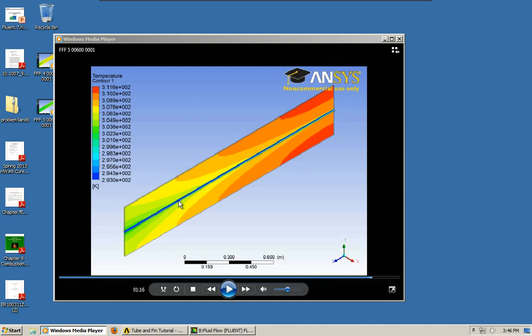If you're concerned with fluid flow and you want to see how the fluid front is flowing in, you have to first patch the volume with air if that's what it originally contains. You can also patch it with a different fluid, but let's say it's a pipe with air in it, and then you want to open up a valve and have water flowing through the pipe. You have to patch the pipe with air before you run your calculation, and that's a whole separate tutorial.